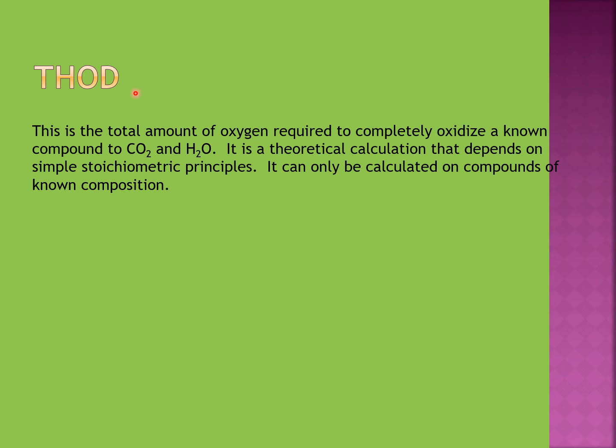THOD, theoretical oxygen demand. It is the total amount of oxygen required to completely oxidize a known compound to carbon dioxide and H2O. It is a theoretical calculation that depends on simple stoichiometric principles. It can only be calculated for compounds of known composition.